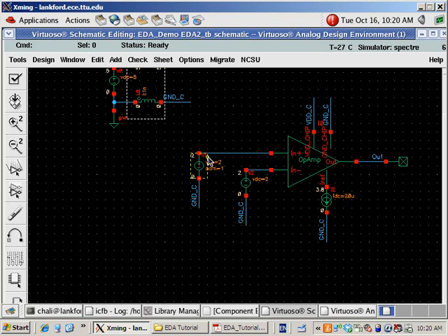And one thing to note is when Cadence simulates the circuit, if you tell it we are doing AC simulation, then it's analyzing the small signal performance. So although I told it 1 volt is my AC signal, it doesn't care. It still analyzes the circuit as a small signal circuit. So in AC simulation, if I give it 1 volt, the output will be 1 volt times the AC small signal gain from input to the output. All right?